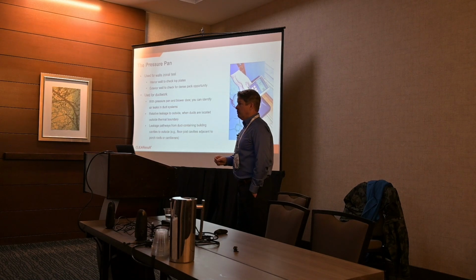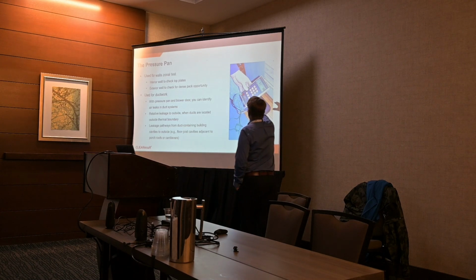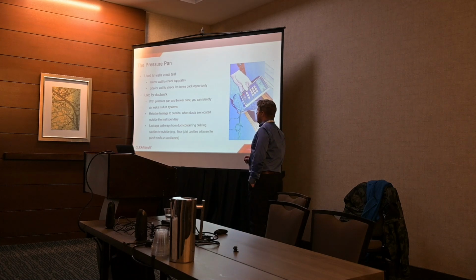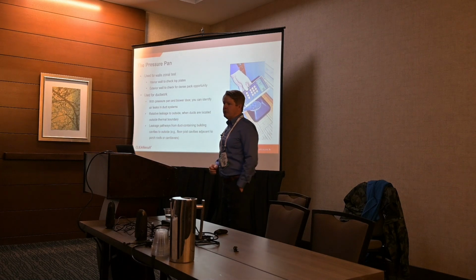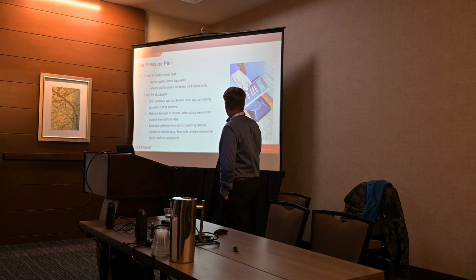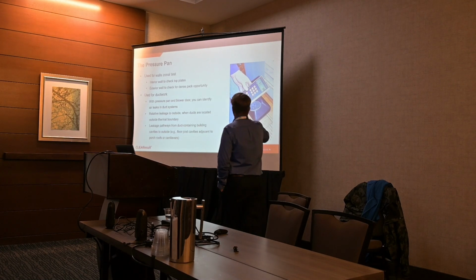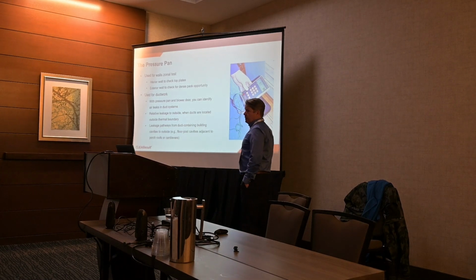Less than 1, right? If we go around and each of these readings is less than 1, you don't really know how tight the ducts are, but you know they're pretty tight. Probably not good candidates for duct sealing, okay? It doesn't quantify it, but it tells you how tight they are. It'll also tell you where they're leaking, right?